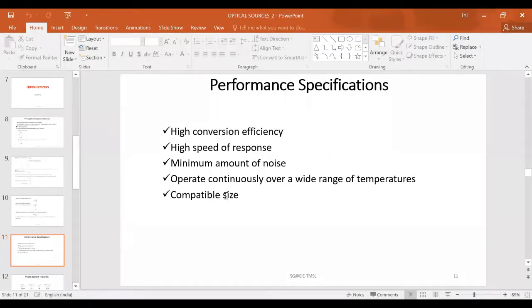So at present, these requirements are met only by reverse bias PN photodiodes. In these devices, the semiconductor material absorbs a photon of light, which excites an electron from the valence band to the conduction band, just the opposite of photon emission. The photon-generated electron leaves behind a hole, so each photon generates two charge carriers. The increase of the material conductivity, the so-called photoconductivity, results in an increase in the diode current.